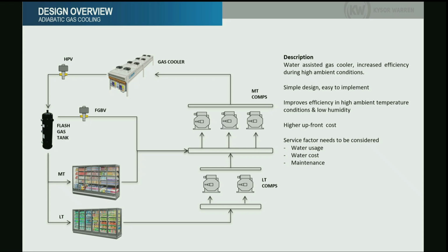Also, because you put water in the system, your cooling capacity increases a lot more. So your gas cooler reduces in size, but you have the water use in the store. Okay? So it provides energy benefits and space benefits, but in the end, the cost analysis, if you include the cost of the equipment, the water use, and the maintenance that you need to provide, needs to be analyzed to decide, okay, I want to use this technology or there is something different. But again, this is the most commonly used.